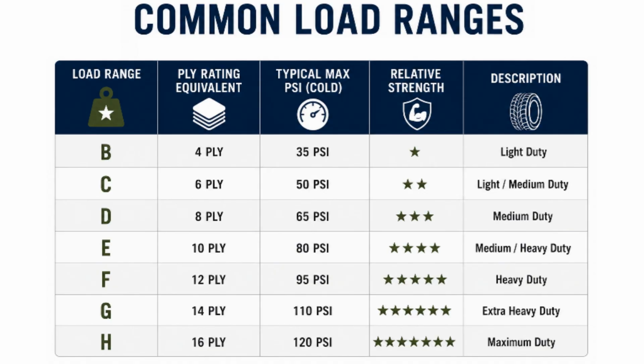Remember, ply rating is a strength classification, not necessarily the actual number of physical plies. Final selection must still consider the manufacturer's load table, actual inflation pressure, vehicle load, wheel rating, speed, and operating terrain.